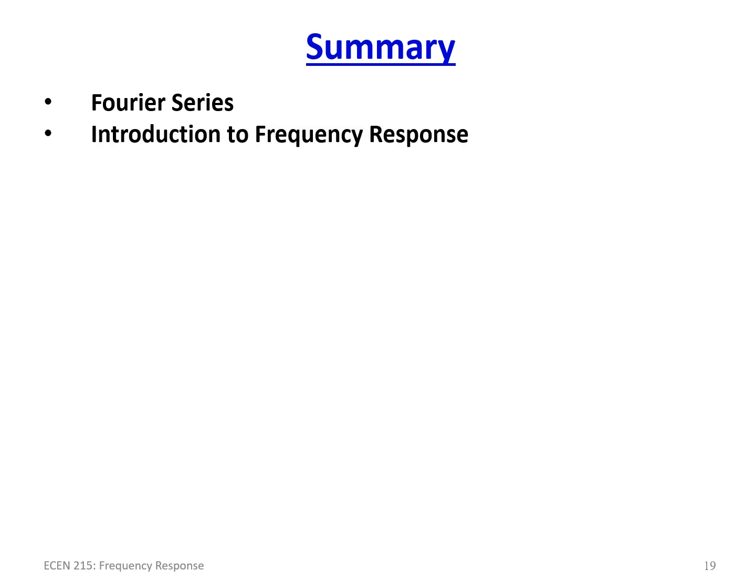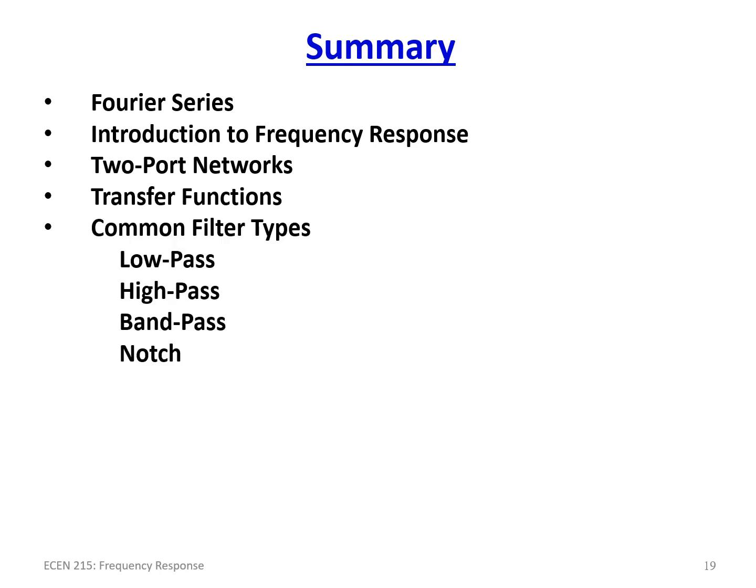We gave an introduction to 2-port networks, an input and output, and coming up with a transfer function for a specific circuit, and what transfer functions look like, their magnitude and their phase. We also talked about common filters used in instrumentation and processing, which are the low pass, the high pass, the band pass, and the notch filter, also known as the band reject.